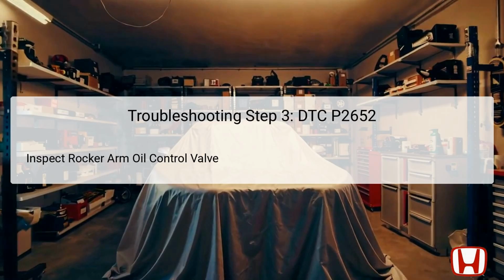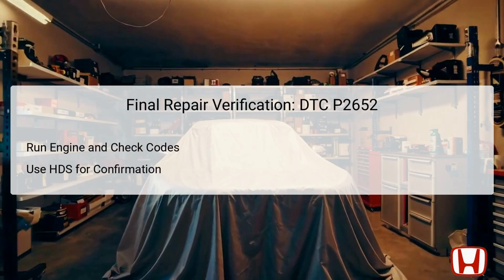A properly functioning rocker arm oil control valve will ensure that the oil pressure does not remain high when the oil control solenoid is deactivated. Identifying a failure here could confirm the source of the problem associated with DTC P2652.